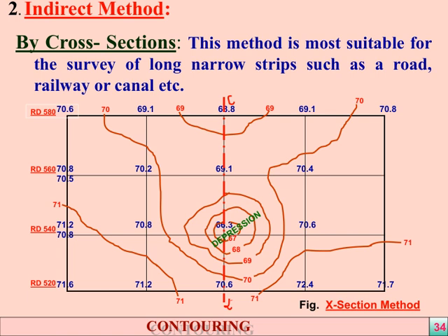Notice the elevations recorded at various stations, with the readings such as 70.6, 69.1, 68.8, and so on. These values are crucial because they help us analyze the land profile. The difference between the high and low points indicates the depression or the slope of the terrain.